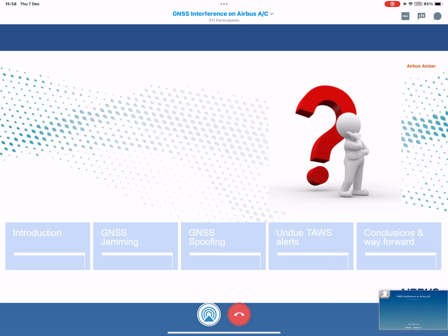So the spoofing is a very complex activity for the one who wants to spoof. And to be successful, it must maintain a very high quality and performance of GPS signal. As indicated earlier in the presentation, it must respect some requirements in terms of code phase, synchronization, alignment with the real GPS signal to be detected as authentic.